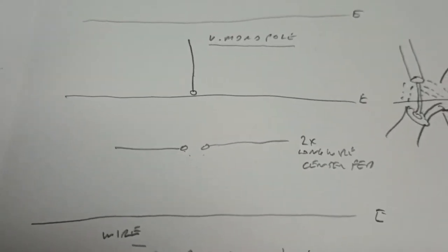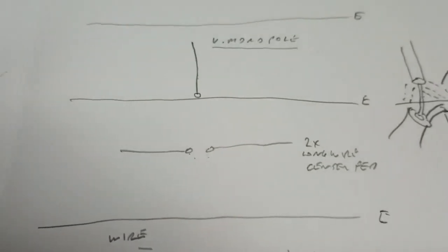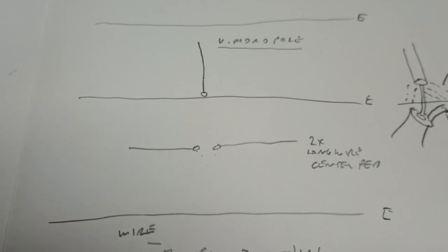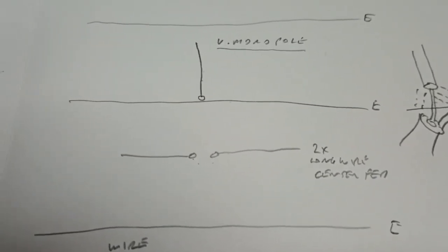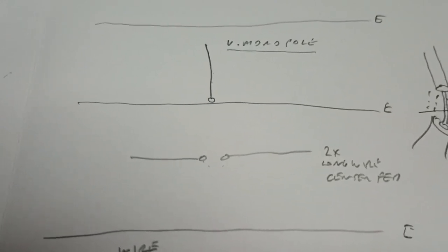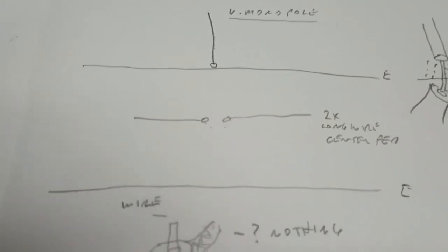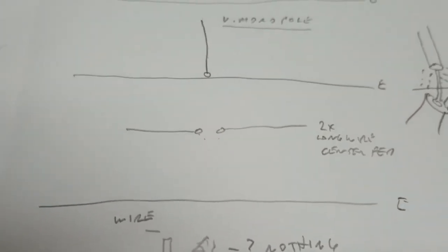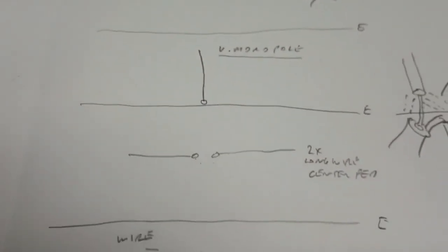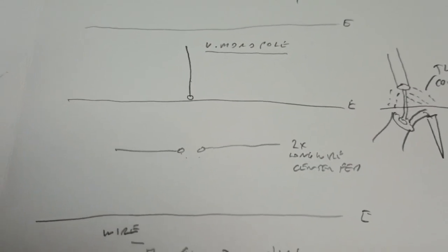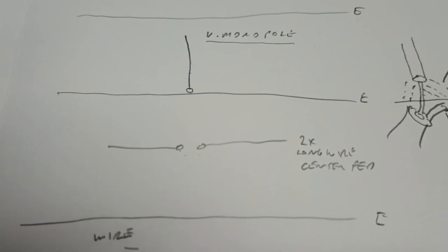And the only way to tell the difference is with time domain reflectometry. If we get a reflection that's at the time of the energy arriving at the feed point, then it's a feed point mismatch. If it happens about a half wave later after going out the antenna wire and coming back, then there's something wrong with the length of the wire, or the antenna is not straight, it's bent, which is why we don't want an inverted L. They're crap also. But something is wrong. The propagation out and back the wires is wrong.